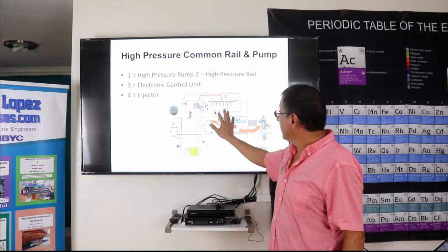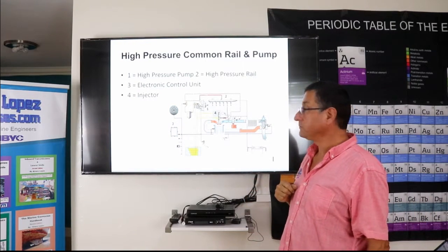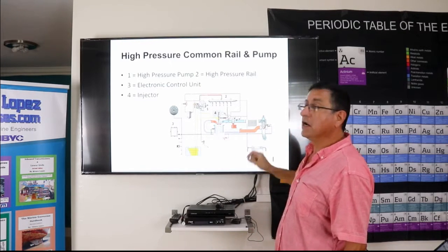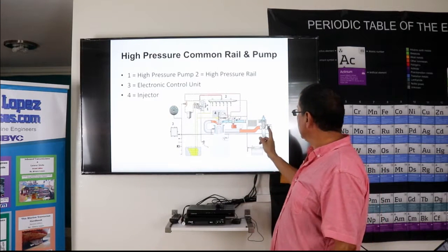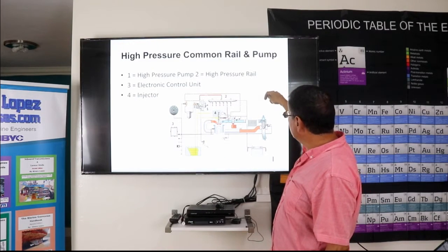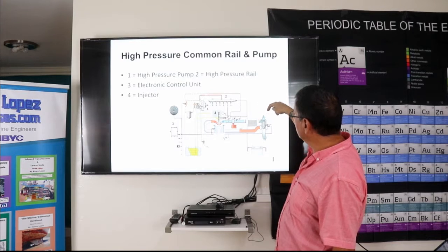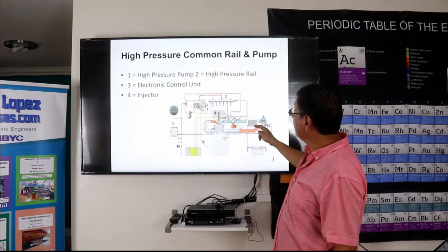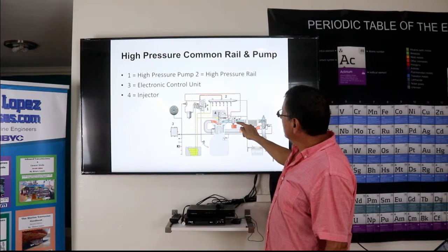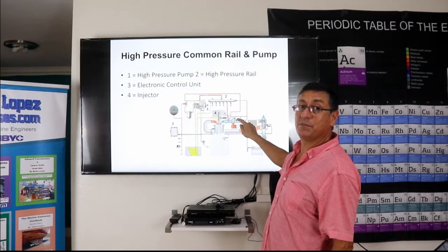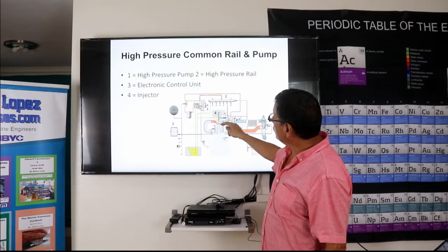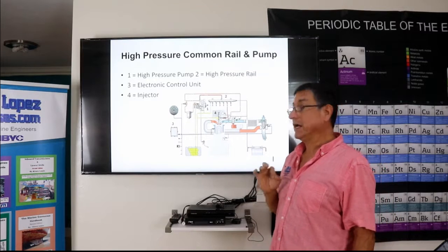That picture is of a typical diesel engine with a turbocharger. If you check, this is the exhaust manifold. The exhaust manifold goes into the hot section of the turbocharger and spins it, and the impeller on the other side sucks in air from the air filter. The air filter is located here, and the air at high pressure passes through the intercooler in order to reduce the temperature of the air. The air continues. We have the intake air temperature sensor here, and the air enters the combustion chamber with the appropriate pressure and temperature.